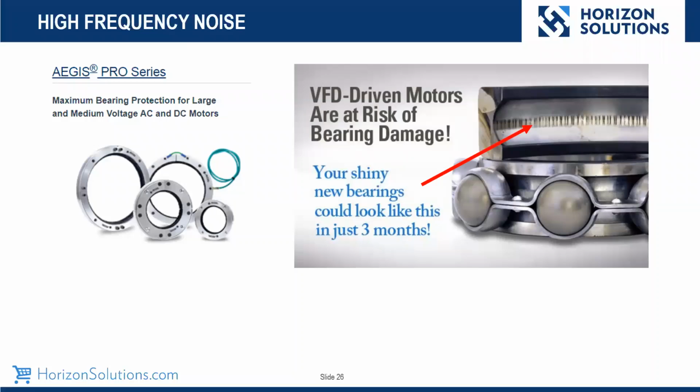Remember, the carrier frequency of these drives is between 2 and 10 kilohertz. You get a lot of circulating currents that go up and down the cable, especially if you don't use VFD cable. This becomes more of an issue, more predominant. All these circulating currents are going all over the place in the kilohertz range.